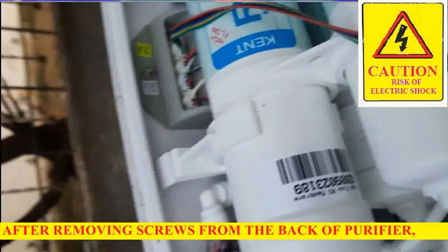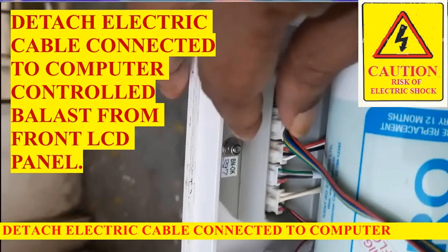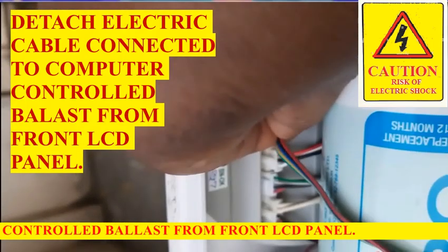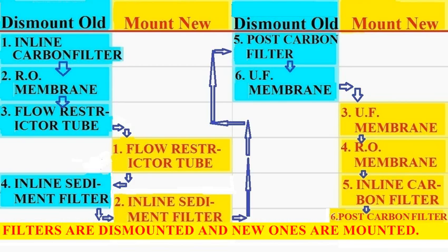After removing screws from the back of purifier, detach electric cable connected to computer-controlled ballast from front LCD panel. This is the order in which old membranes and filters are dismounted and new ones are mounted.